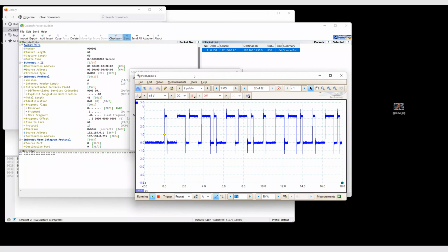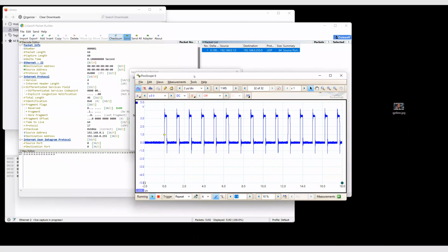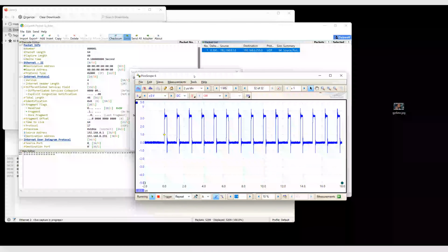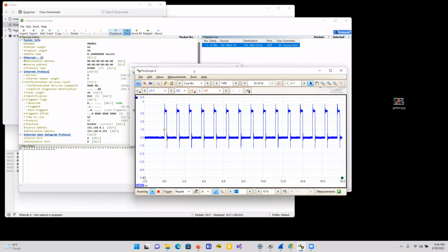What's good is that certain ones, if they're connected, it mostly works, so you can debug it fairly easily. If it's not transmitting or it's not receiving, it's probably those wires. What is interesting is there's a 50 megahertz clock that comes from this board that clocks the Pico, and I'm running over quite a bit of wire. That's why I think it's mostly working, which I'll show you what that means.